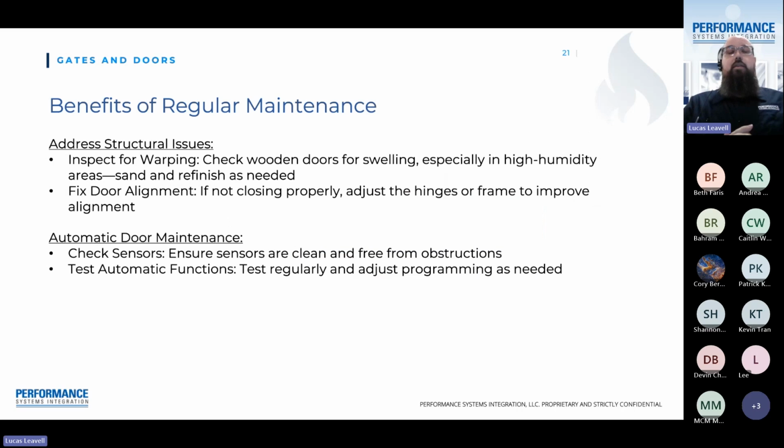For anything that involves wood, it can swell. And if you have a door that is rubbing, the most common cause will be a hinge. However, if the door is between two environments, such as the inside of your home and the outside, moisture can also intrude in there, which can cause the door to swell. This can usually be corrected with a simple sanding down of the surface of the edge of the door, but sometimes it will eventually get to the point where the door is no longer operable, especially if the door starts to get stuck in multiple places.